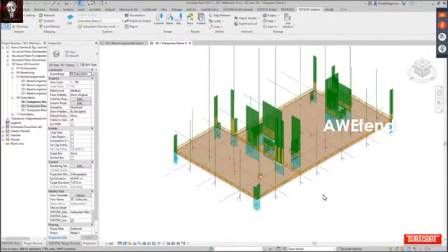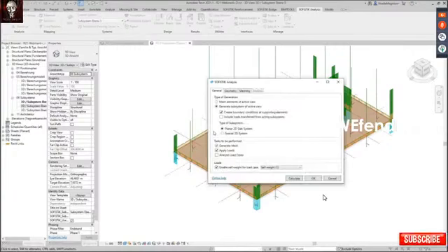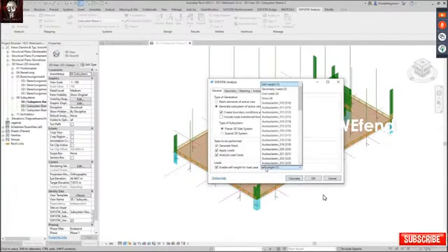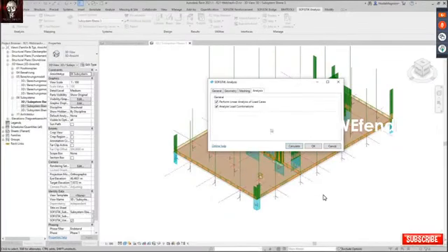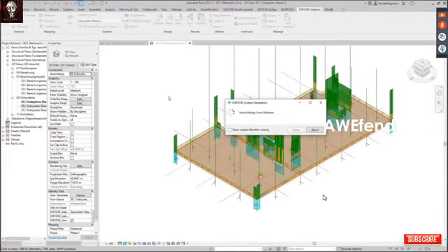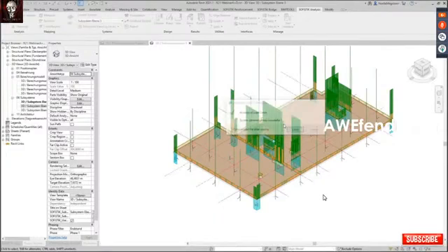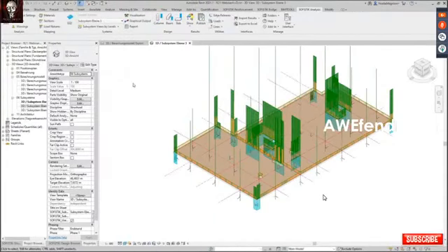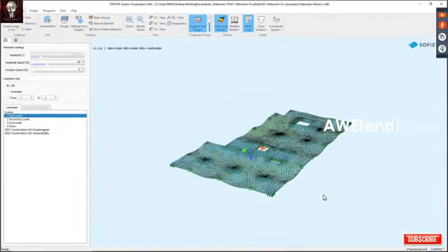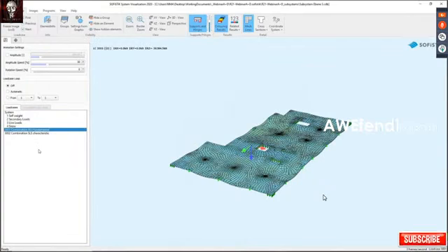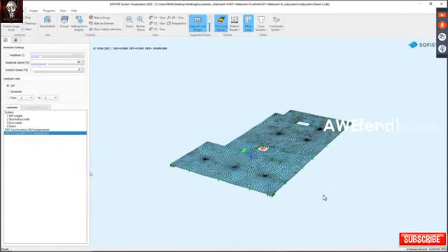Once I've generated my global load combination, I will analyze my subsystem. Just to show you, this drop-down menu is now reworked. It's a bit new. And I will activate the analysis of load combinations too. So like my colleague showed already previously, the subsystem is generated in the background, and I can see in the visualization now my subsystem with single load cases, but also the two combinations which I just defined previously.